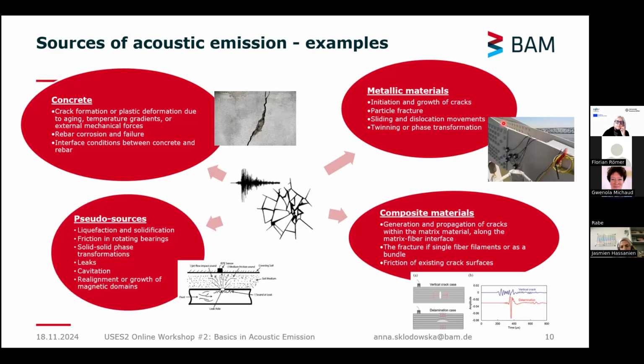There's also a bunch of so-called pseudo sources. This could be liquefaction and solidification, friction in rotating bearings, solid-solid phase transformation, leaks, cavitation, realignment, or growth of magnetic domains. As I said, there is much more. We also have ceramic materials, wood, and so on. So this is just a few examples of the sources.